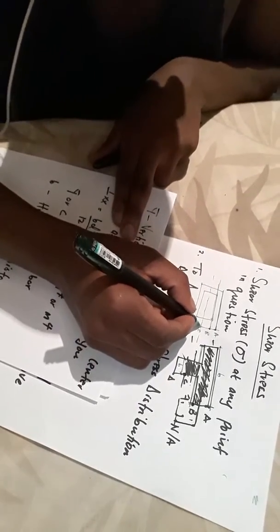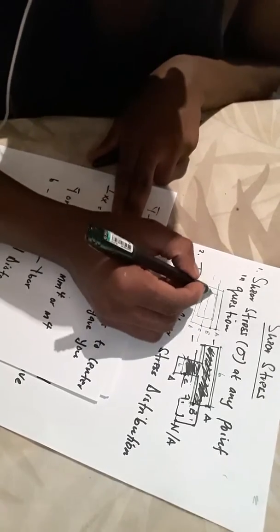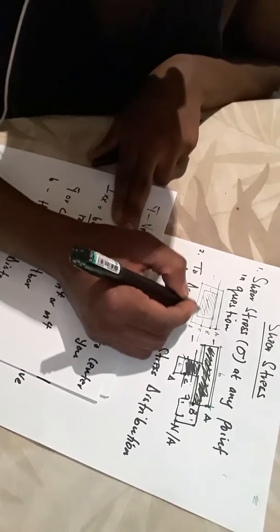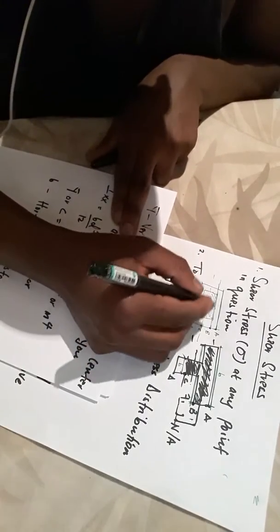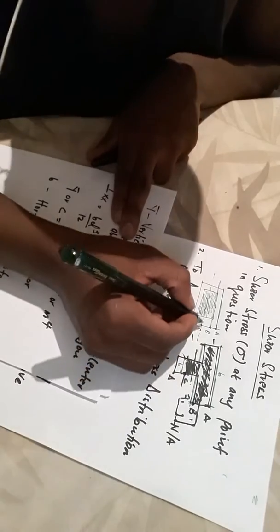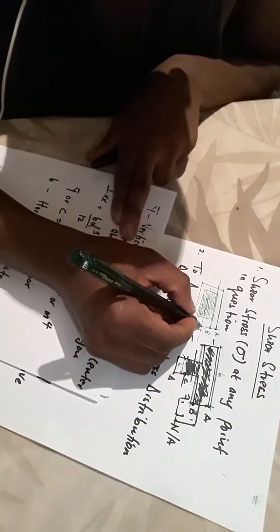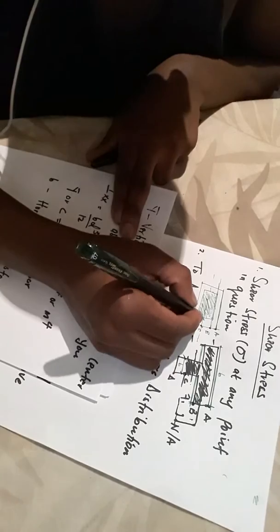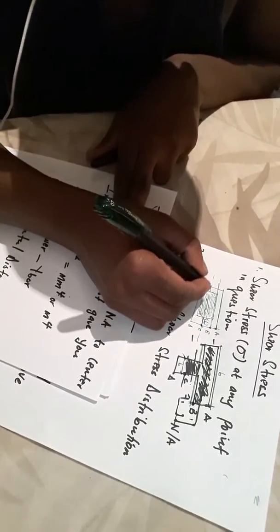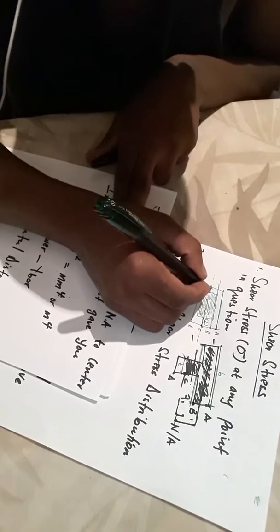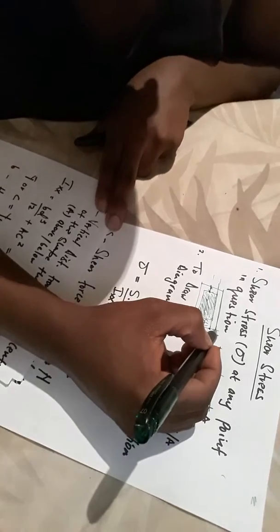So when you're calculating shear stress at C, we can see here that there is a hollow section. So in this area, it's a hollow. There's a hole here. So when calculating shear stress at C, this will be your B on this side plus this B on this side. So that is this B from this formula means this is the horizontal distance from the point in question.